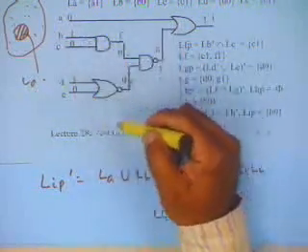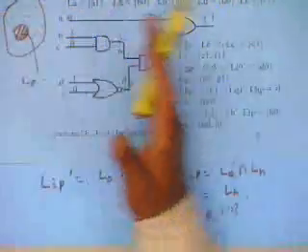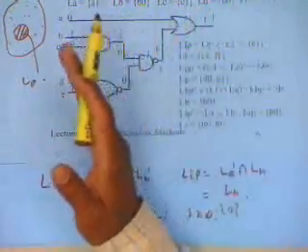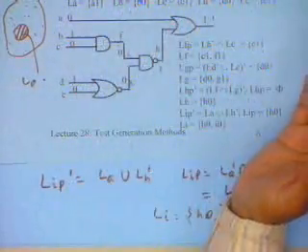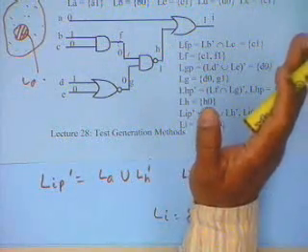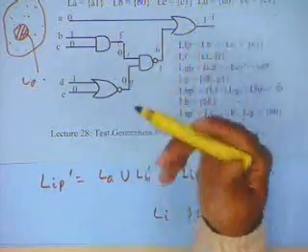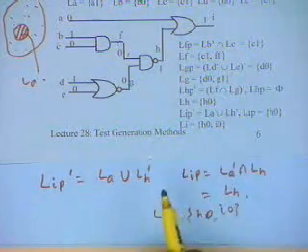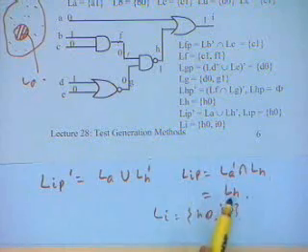And so by replacing this circuit by this and making one single evaluation, you see the basic difference is, unlike in the case of parallel, here also we are given a test vector and I am generating the set of faults. But in parallel fault simulation I have to keep on evaluating the circuit a number of times because I can only evaluate one at a time. Here of course I have to maintain more complex structures because this list could be very long.